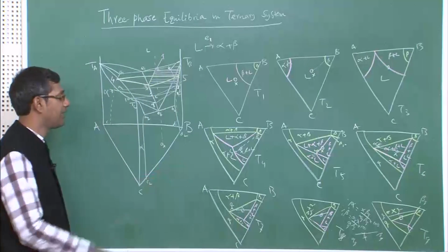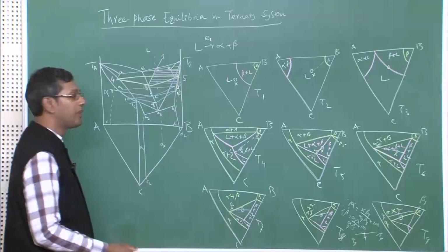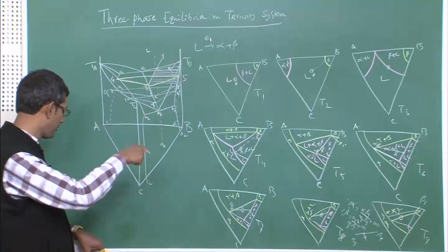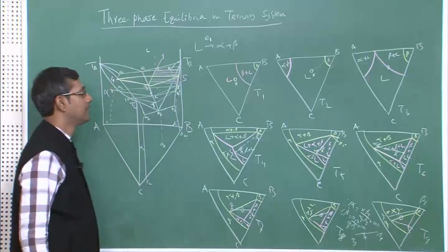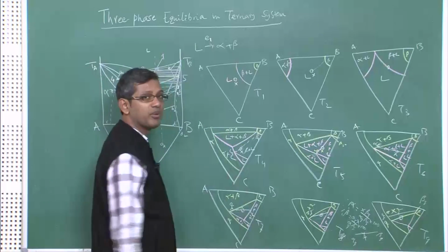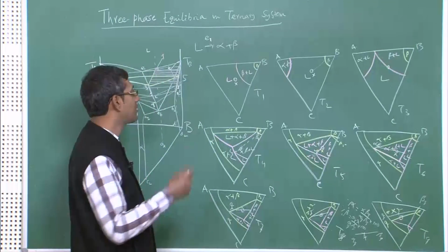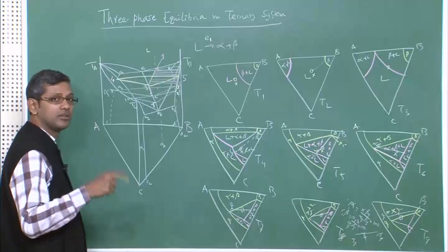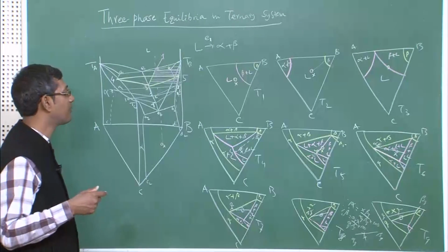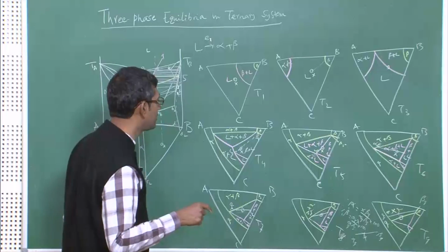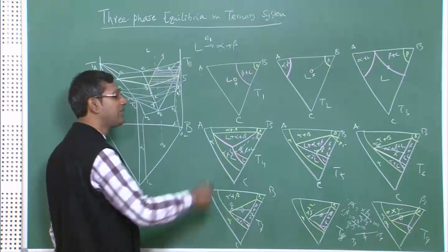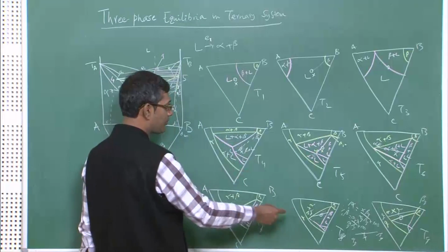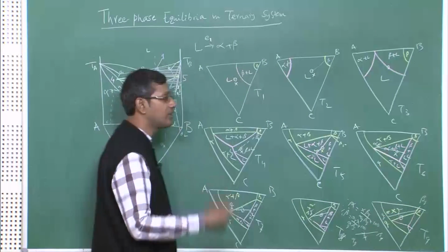Because of space I am just writing there. So, although it might be difficult for you to follow the solidification pathways in this, you can follow the solidification pathways nicely here. Basically, once you are able to draw the isothermal sections nicely, it is a matter of just putting a composition point there. Remember, the liquid composition keeps on changing, as more and more alpha and beta are forming. Because of that, this point is also moving, it was initially here, then it moves there, then there, then there. You can see here how the things are changing.